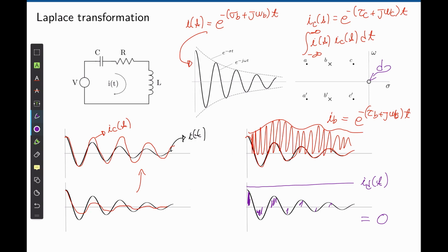Here we identify three cases. The first case is a very large number, the second case is 0, and the third case are smaller numbers that have no interest in the Laplace transformation. These values represent points that don't match exactly the signal we are looking for, whereas a point where the signal goes to 0 is a so-called zero of that signal, and points where the integral tends to a very large number are called the poles.